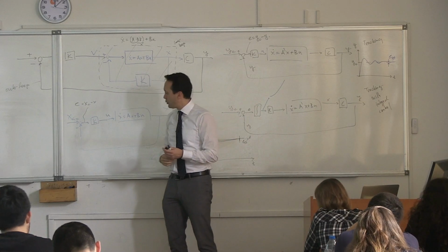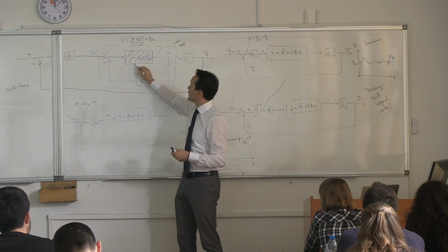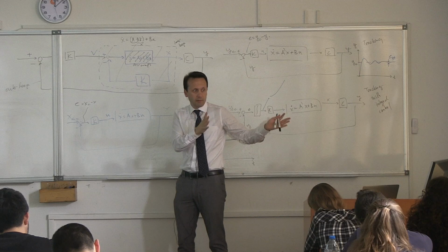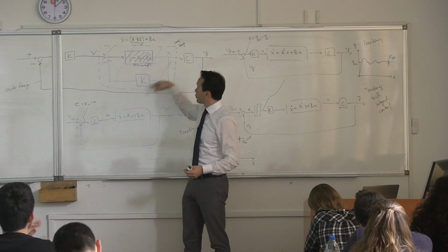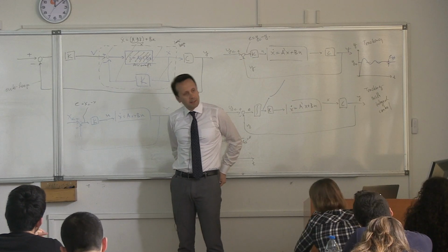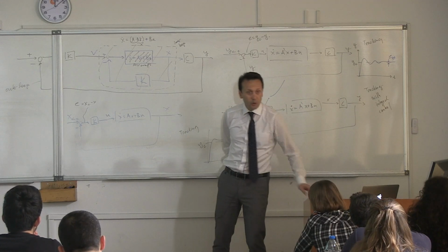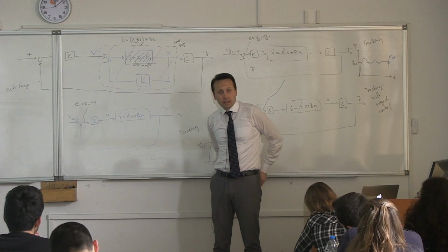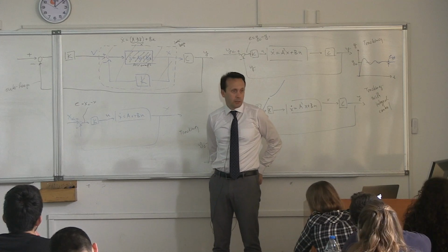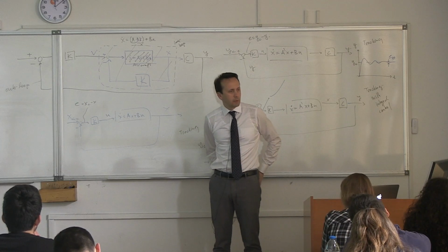What happens in real life, of course, is you replace this x dot equals Ax plus Bu with the real plant. This is now the aircraft. Okay? So you don't have the linear model, it's the full aircraft. Which means that your controller will only work at the design point, which is the linearized point at the equilibrium point and so on and so forth. And if you are going far away from the equilibrium point, it will still work as long as the system is sort of linear. If you lose the linearity and you get a lot of non-linearity, then it will not work anymore. So what do you need to do? You need to redesign controllers at different operating points, basically.